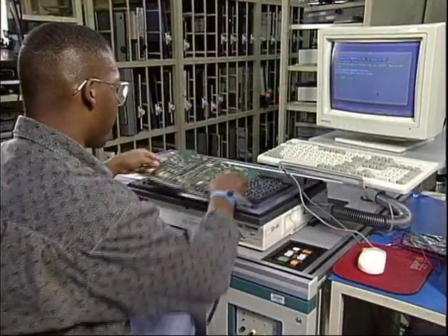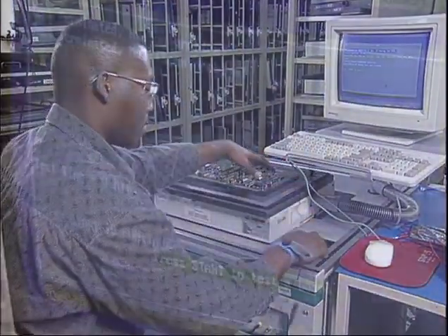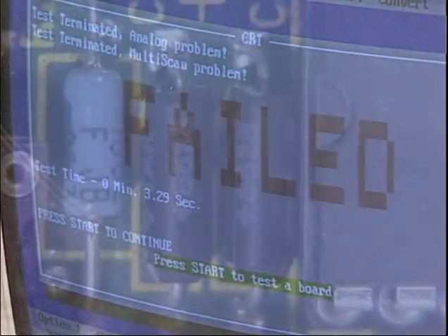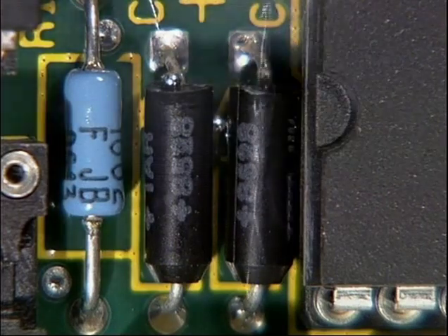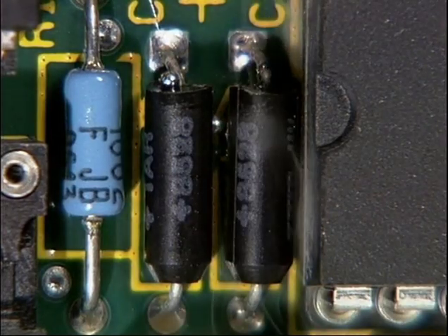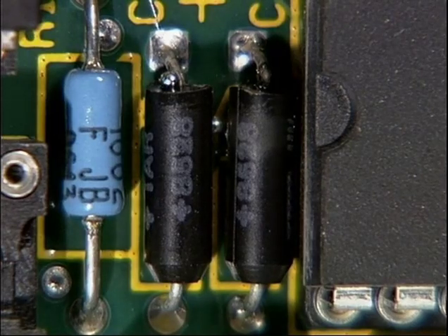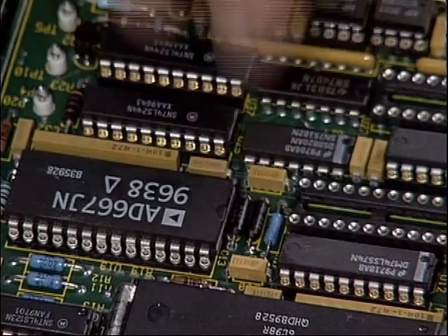When a component is not oriented correctly, the assembly won't function as intended and will fail electrical tests. When a component is inserted with polarities reversed, the component can actually be destroyed. There may also be damage to the circuit board. The result can be costly repair work or even a scrapped assembly.